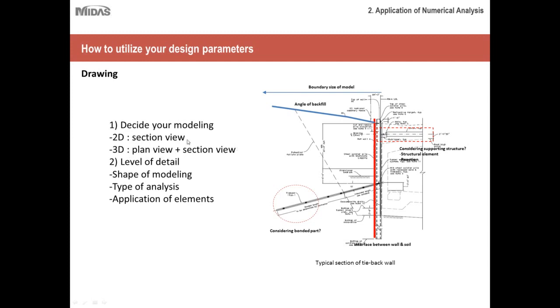But just keep in mind that 2D analysis is much faster, it's much more efficient for smaller projects, whereas 3D analysis takes a much longer time, but it's something that needs to be used for larger scale projects. And then the level of detail, shape of modeling, the type of analysis you want to do, make sure to have these parameters defined beforehand so that you can plan out how you want to do your numerical modeling.